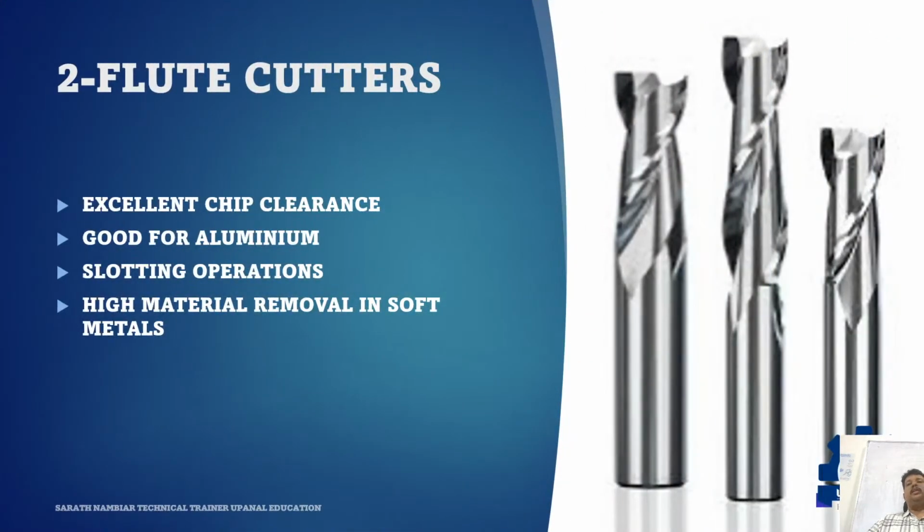Now, two flute cutters. Let us begin with the two flute cutter. A two flute cutter has two cutting edges and large flute valleys. This means that chips can escape easily. That is why two flute cutters are very popular for softer materials.